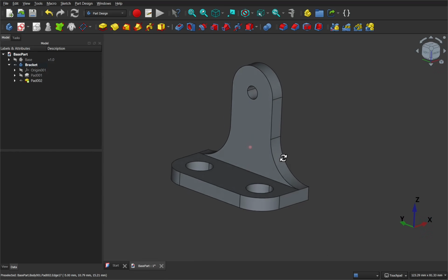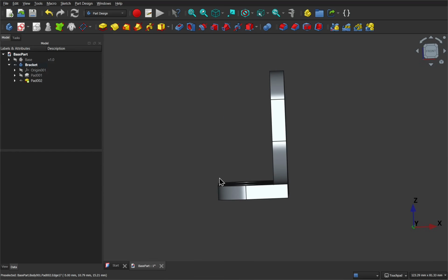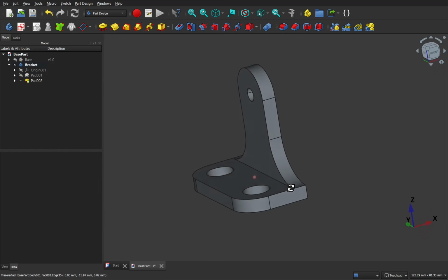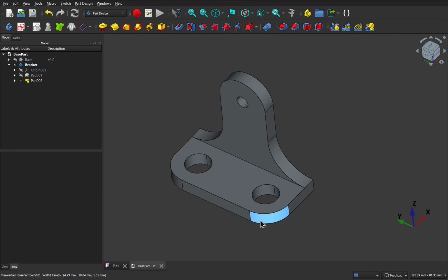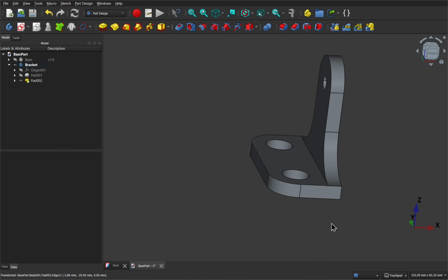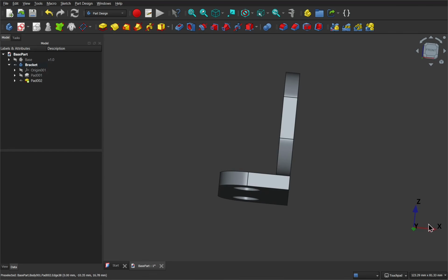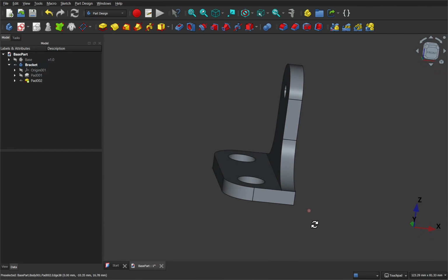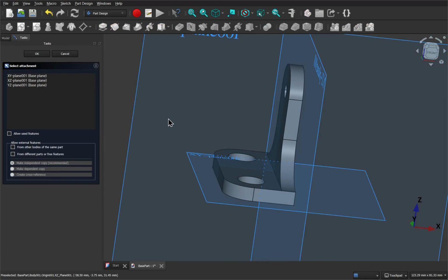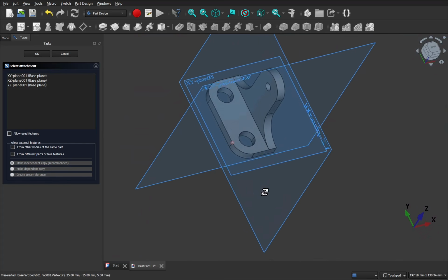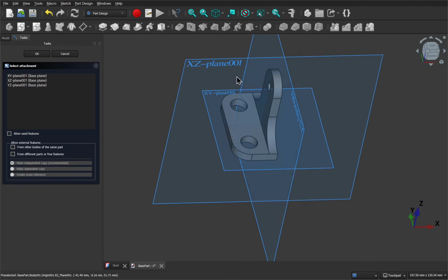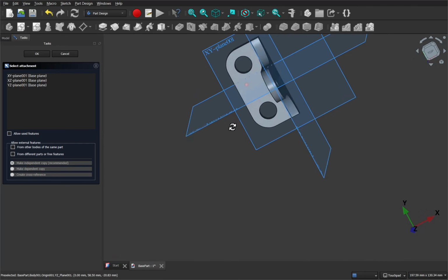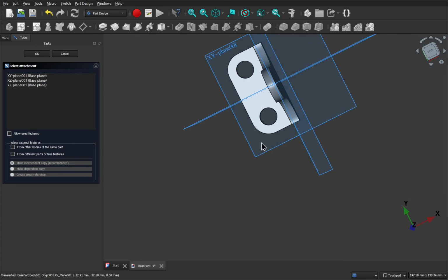So I want to create a sketch from this side, a triangle that sits in the middle, which we'll pad from. To do this, we obviously need to be on a different plane, the XZ plane. Now there's two ways of attaching the sketch. We can make sure that nothing's selected and create a sketch. This means that we'll attach to the base plane of the active body. So we've got these planes back up and I can pick the XZ plane. And because we've modeled this over the center, it fits nicely with our model.